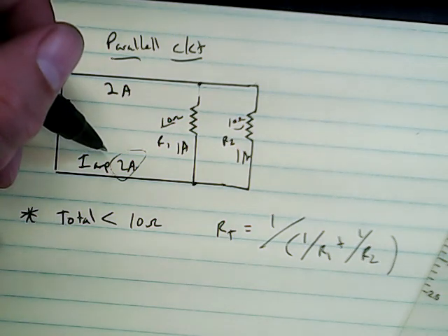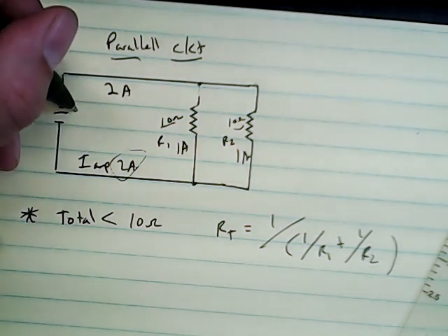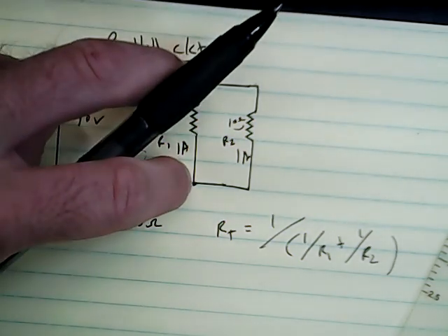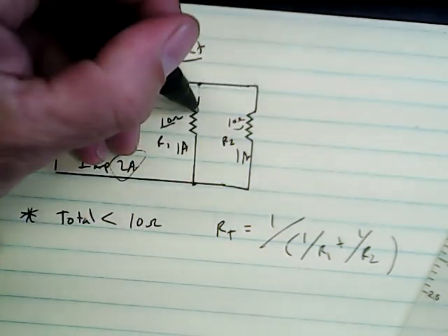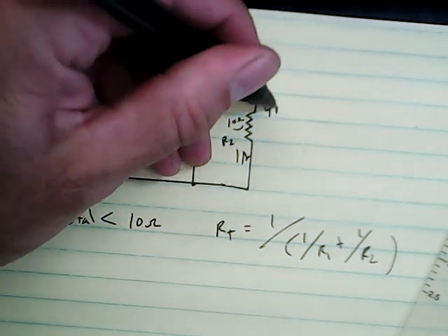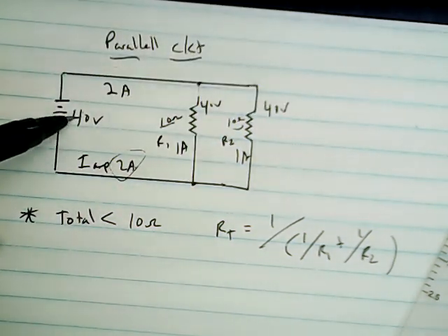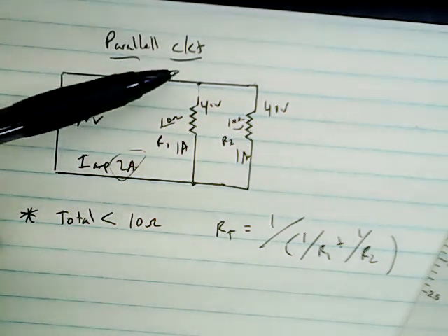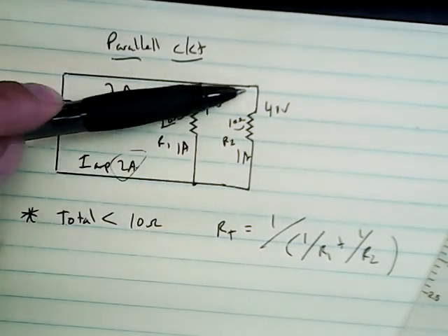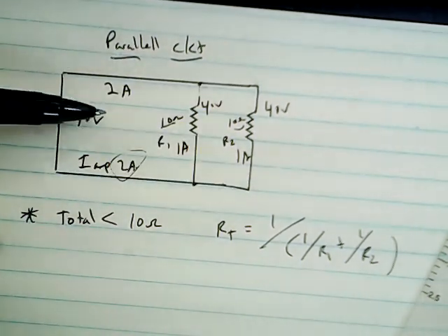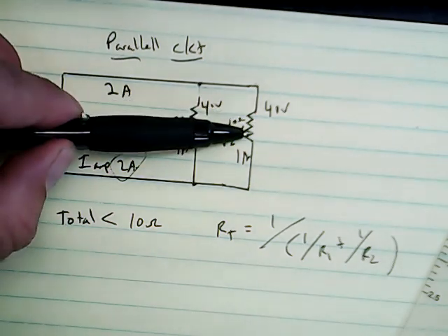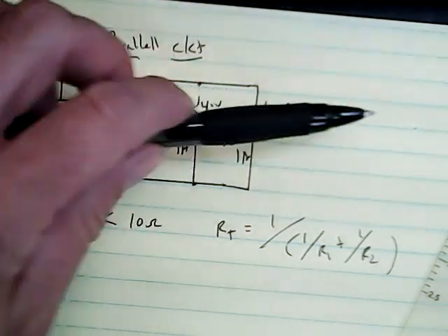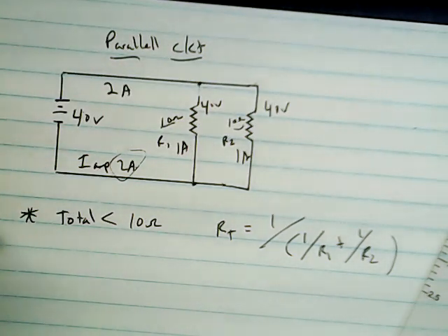Voltage, it's the easiest one we got out there. So if you have a voltage total, so let's go again, let's just say this is 40 volts total, we know that in a parallel circuit, the voltage is going to be the same across both values here. So this would be the same 40 volts again. That's really the biggest difference between series and parallel. In series, if you remember, we were dividing that voltage up as they pass through each resistor, but because we have multiple paths for electricity to flow, you're going to see that voltage stay the same throughout each load in the circuit. So if we added a bunch of lights on this or resistance values here, you'd still see that 40 volts all the way across throughout.